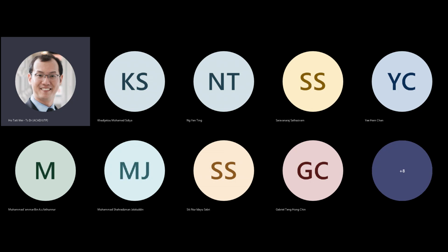So I can raise this silicon to 500 degrees Celsius and nothing would happen to the material, except that the number of free electrons in this undoped region could rapidly rise to such a point where it could swamp the number of free electrons that are artificially created in the n-doped regions. In an extreme situation where you run your MOSFET transistor at a temperature so high that you can't tell apart the p-doped and the n-doped regions, what you essentially have is a slab of silicon with undifferentiated regions. That means your device fails to function as a MOSFET because it doesn't look like a MOSFET anymore.